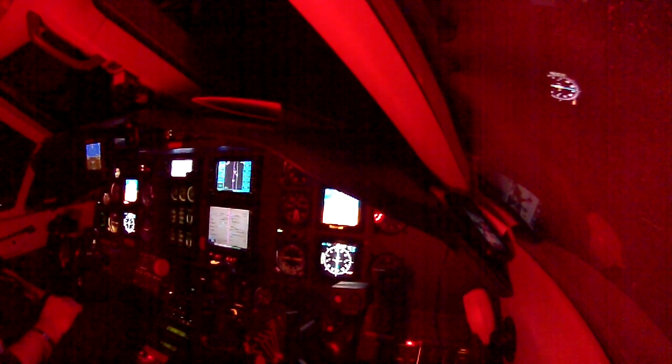So the AHRS, other than providing attitude information for the attitude indicator, will provide heading information for the HSI. Okay? Now, when you're looking at the indication here for the HSI, that's the electronics. How is it on a regular 6-pack? The heading indication comes from the magnetic system.